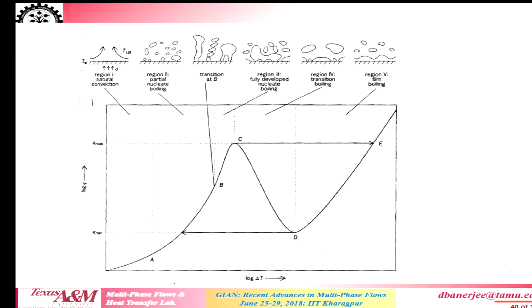And then when you get close to the maximum heat flux point, the rate at which the bubbles form is almost marginally bigger than the rate at which the bubbles depart by terminal velocity in the fluid. And so you have a merger of the bubbles in the vertical direction, and you end up with columns. In certain situations, the columns start oscillating and join with each other, and they trap superheated liquid in between them, and they form a mushroom shaped bubble.